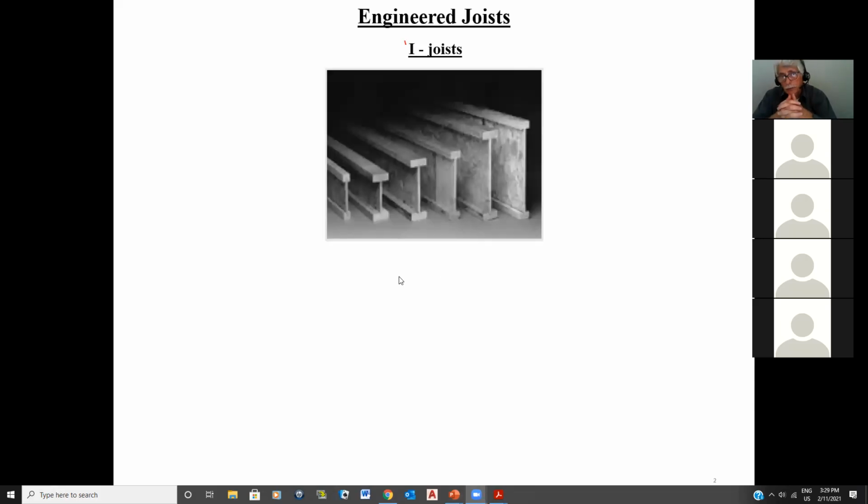That's what they look like. You understand? In other words, the top and bottom chord is made with a piece of lumber. Like here, you see this one's made with a 2x2, this one's made with a 2x3. So these are pieces of lumber. It could be a 2x4, it can be a 2x3, and then of course the web members are made with these OSB boards.